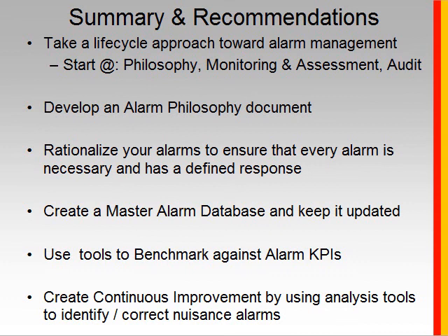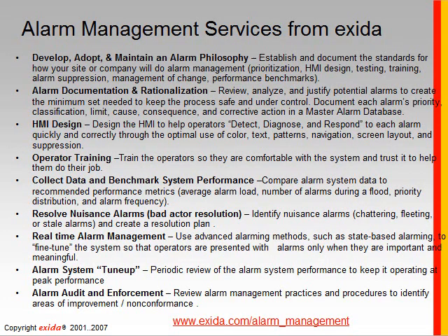When you can identify things that can be fixed or need to be fixed quickly and easily, you can get the operators' buy-in to do more and essentially request additional funding for alarm management projects. So the idea of identifying low-hanging fruit, fixing that, showing progress, showing improvement, and building upon that is kind of a technique or a secret that people use to get alarm management projects approved.